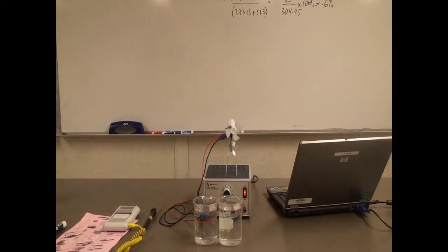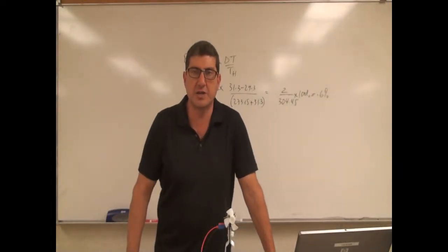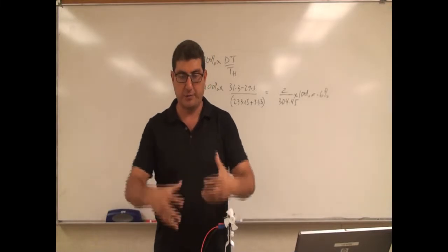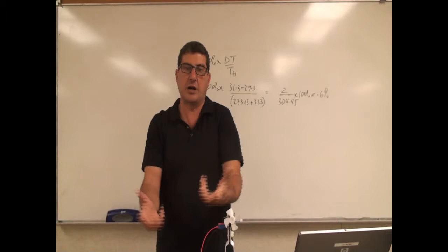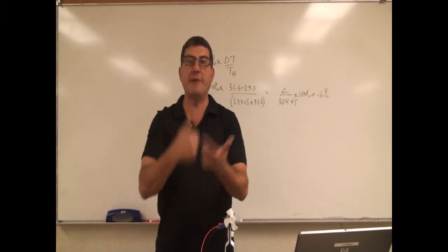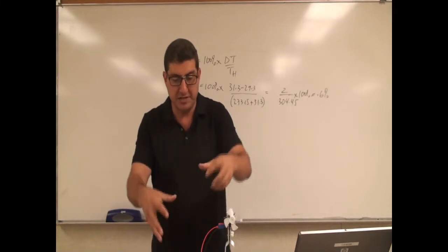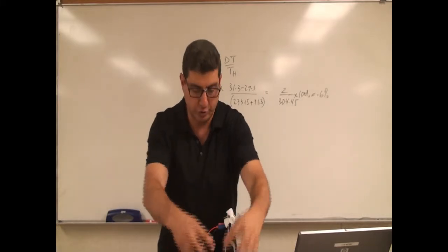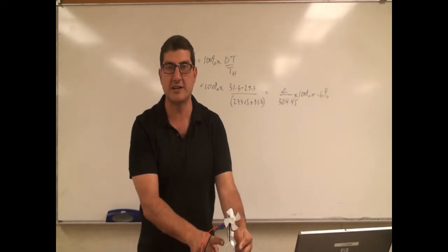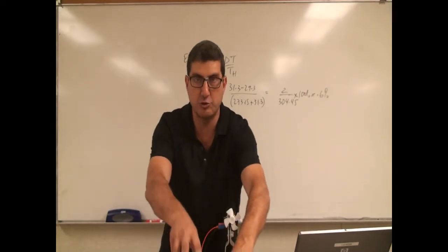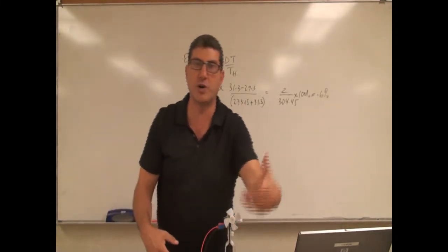Okay? So you can see here how the thermoelectric converter was a good illustration of the heat engine. First, by creating a temperature gradient between the hot and cold water, I was able to run the engine. Then I ran it backward as a heat pump, right? Heat pump, that means I used it as a way to create a temperature gradient. I put in electrical energy, and then the two metals became different temperatures, and then I was able to create a temperature difference between the two waters. One water went cold and one water went hot.